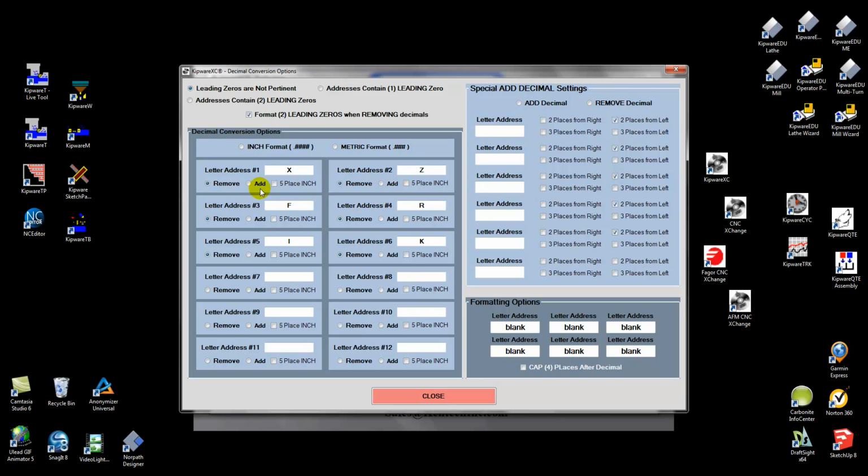In this kind of a combination, you could go back and forth between those two machines. You could go into your FANUC format and convert it to the older machine format. You could also take an older machine program and convert it back to a FANUC format where you do have decimal points and you do have X as a diameter value.